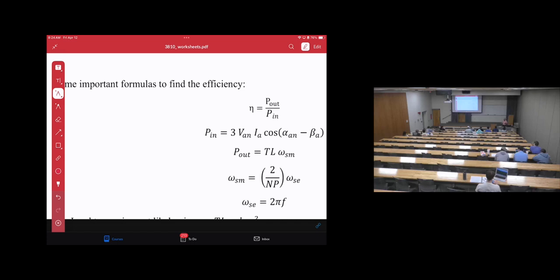Now, someone can say, okay, I need to use the cheapest one. But this is not always true because we have the efficiency. We need to make sure which has the highest efficiency. Because if you buy a motor with 60% efficiency, then you will lose a lot of money in the losses, right? And this will cause heat, overheating, and sometimes this can be something undesired. Therefore, you're going to say to the electrical engineer, please find the efficiency of each motor. So they will give you the calculation.